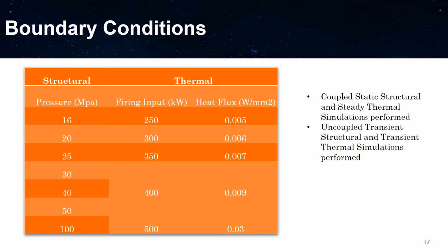We've performed coupled static structural and steady thermal simulations, and uncoupled transient structural and transient thermal simulations, because it was computationally inexpensive, and it was within my range to do on a commercial laptop. Also, one of the reasons I did uncoupled is that there were no thermal stresses involved, because the injector could deform on the z-axis freely due to thermal expansion. So there were not many thermal stresses involved. That's why I intended to do uncoupled on the transient one.